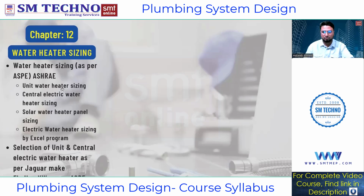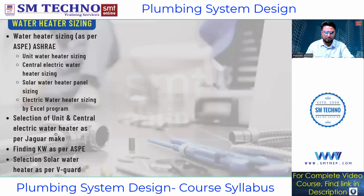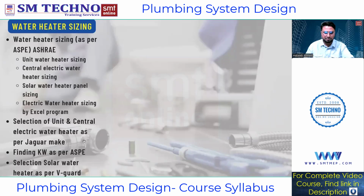Once you have obtained the capacities of unit, central and solar water heaters, one can do the selection from the catalog from Jaguar. Okay, so one can find out what the make or the model number should be. And the most important thing, we being mechanical graduates, when we are dealing with the water heater sizing, it's our responsibility, or we are the concerned person who can give what is the kilowatt needed for this heater to run. That is for electrical water heaters, I am saying.